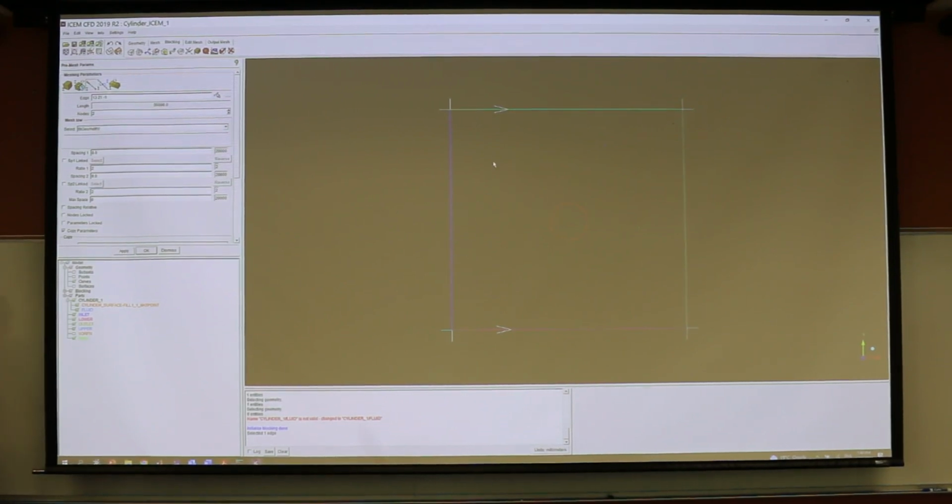For example, if you would like your mesh elements to be smaller here and larger there, you can define the spacing, and you can define the equation and the expansion rate for that spacing. This is very useful in the boundary layer treatment or in any regions where you would like to have a very coarse, a very fine mesh. So for example, I like at the beginning to select copy parameters.